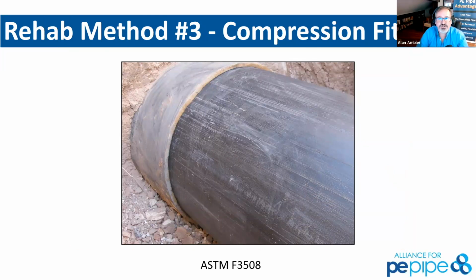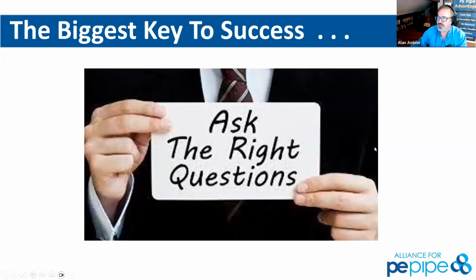We had a good question about what do we do with valves. Those valve locations become excavations. So we just remove that valve, and if we have longer runs, we can pull through, or that valve location itself becomes an entrance or an exit pit. This is similar to slip lining and pipe bursting, in that we're not really going to be able to pull through those valves as we come through.